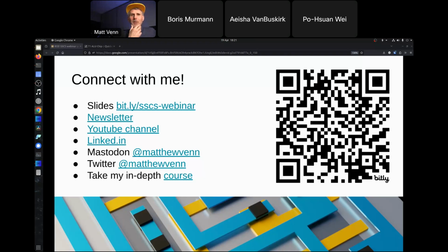We've got KLayout and Magic. Well, let's actually start with schematic capture. There's Xschem, that's the main one, but there's also Qucs, and some people even use KiCad, or you could write just Spice directly if you wanted to. But the first part is analog capture. Then there's simulation, ngspice. Xschem and ngspice work pretty well together.